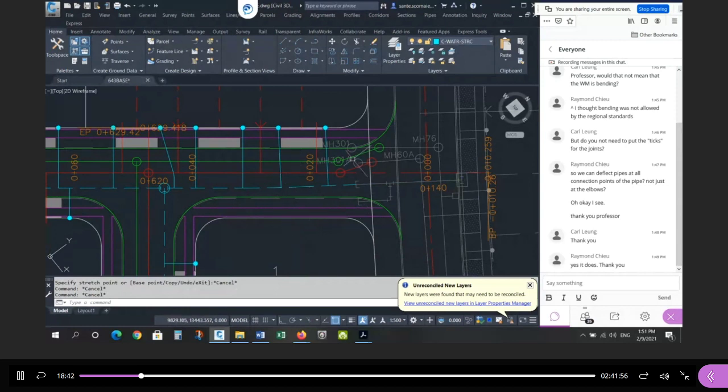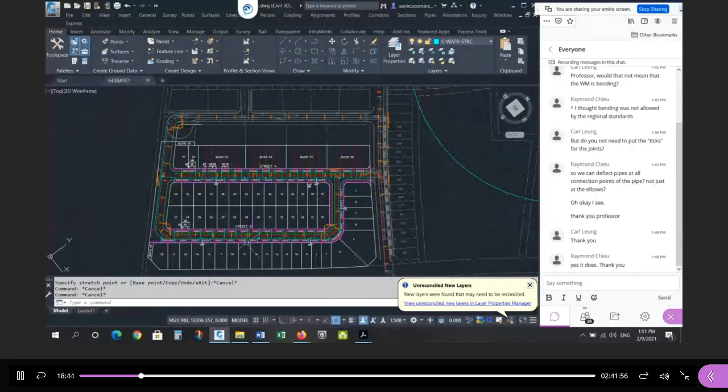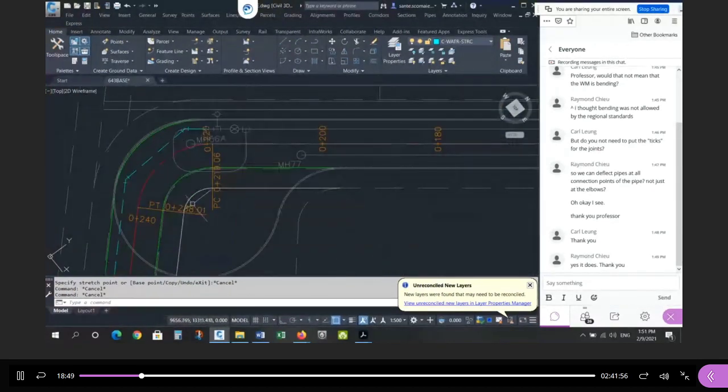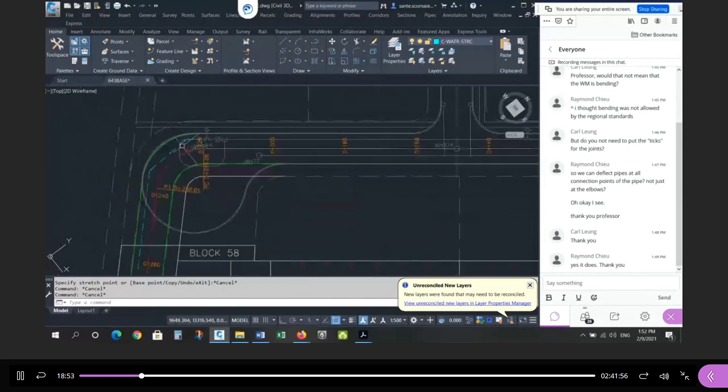So that's how I made my connection here. Okay, the water main connections in the corners and up here are all 45s, even if it's not exactly 90. That's close enough. Here you can do joint deflection on the fixtures to achieve the change in direction.